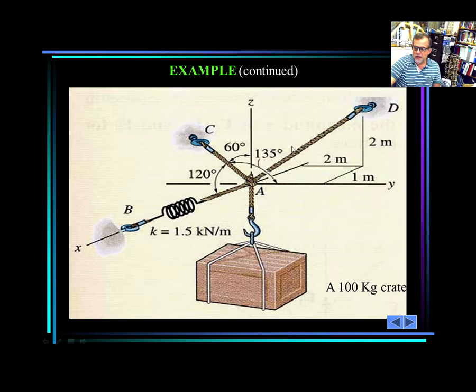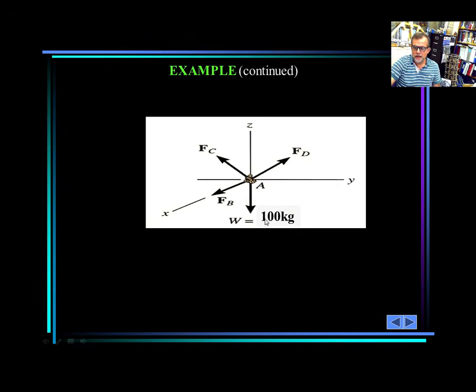Okay, a little bit bigger for you. Now, I have the 3 forces and the crate, and everything is in equilibrium, so I have to find that force, this force, and the weight. That's going to be my free body diagram, basically. And this is not complete, of course. Why is it not complete? Because this is mass and we need it in weight, and I'm just doing emphasis on that because a lot of students mess up with that.